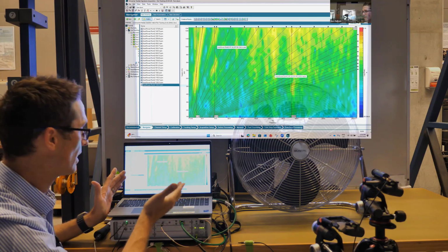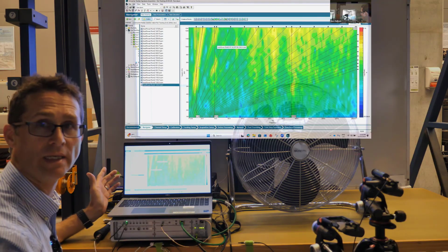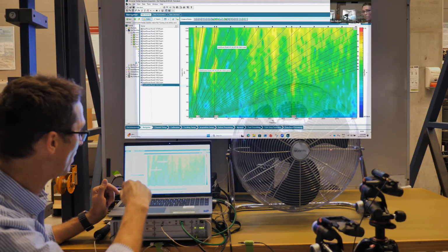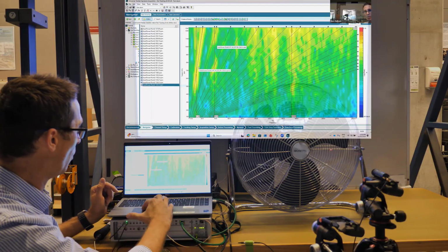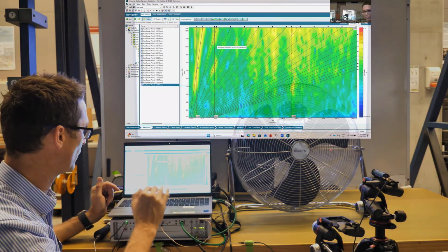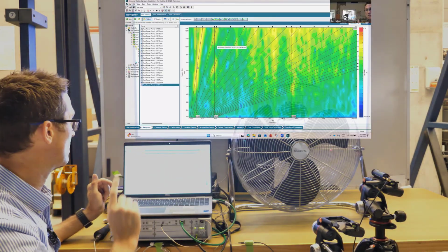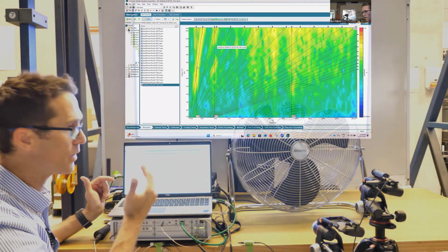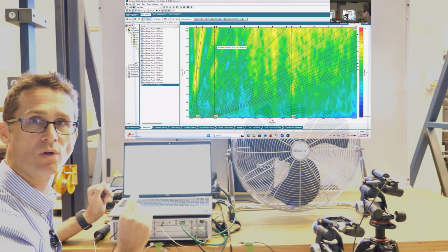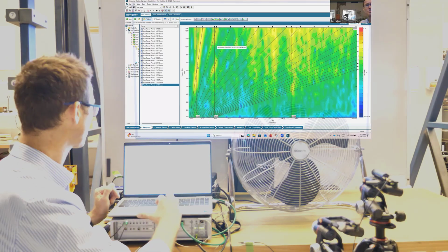data appear. You know, in as much as this 11 hertz peak, for example, in the frequency response function for this structure, didn't have a huge level compared with some of these higher order levels, but when the forcing function coincides with that natural frequency, then we really see the vibration level increase, and that's the meaning of resonance. That's why we look at vibration data on a logarithmic scale on the y-axis, because even the smaller peaks can be important when we drive the structure at those frequencies.